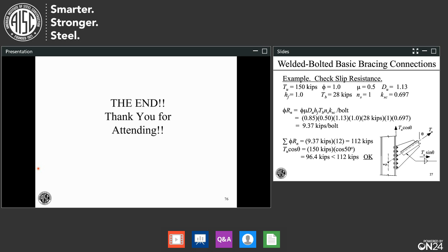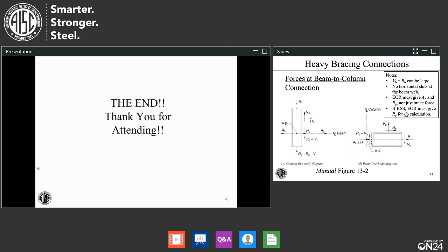All right. Let's move to slide 45. And on this slide, you commented not to use slotted holes in the beam-to-column connection. And somebody asked, would you find it acceptable to use slotted holes for that connection if you were to use a slip-critical connection?